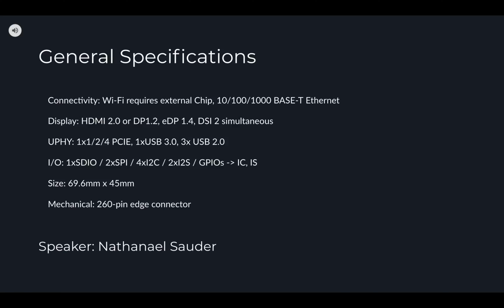For input outputs, we have 1 SDIO, 2 SPIs, 4 I2Cs, 2 I2Ss, and a GPIO. The size of the device is 69.6 millimeters by 45 millimeters. It also has a 260 pin edge connector.